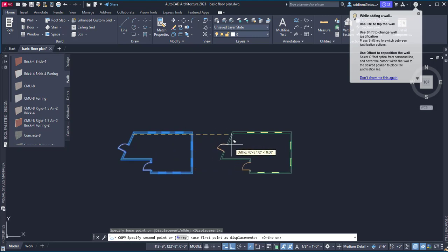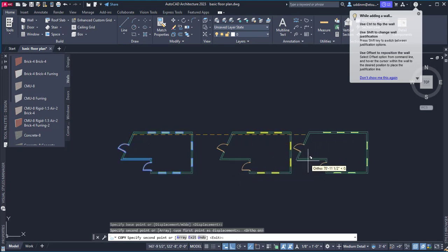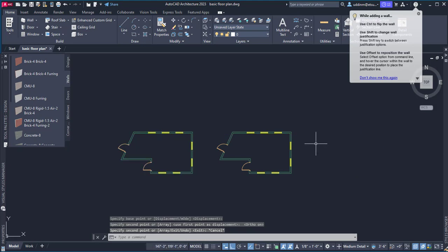So if this is two floors, for this residence that we're designing, you just copy one time. If it's three floors, same footprint, just copy it again. As we mentioned earlier, to get out of this, just hit escape. We just want to deal with two floors.